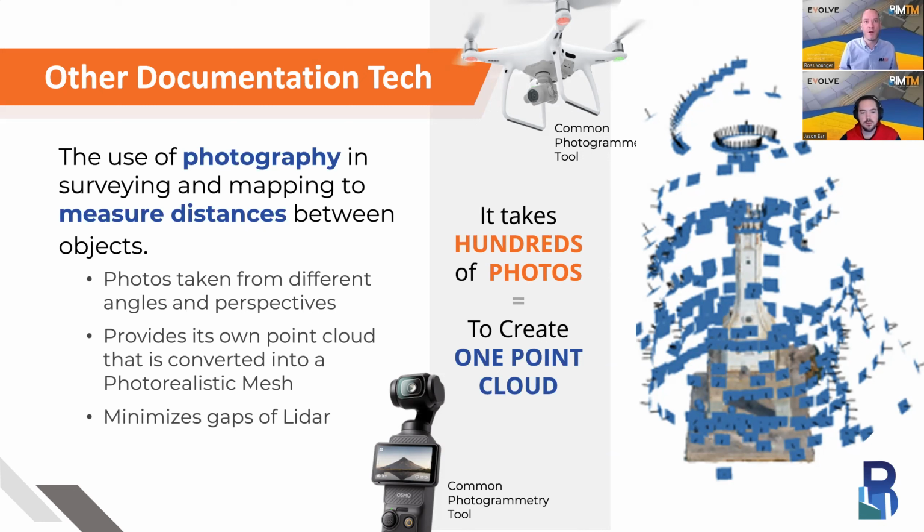The main advantage there is that you're able to minimize gaps that you might have with the LiDAR. No matter how many scans you have, there's certain situations where LiDAR is going to be a little limiting. I don't think that there's a 60-foot tripod for a LiDAR scanner that can be used dependably, and so combining that with drone, with point clouds generated elsewhere with drones, or with even just a handheld camera where you can put it on a selfie stick and poke it up where you need to, can certainly be helpful.